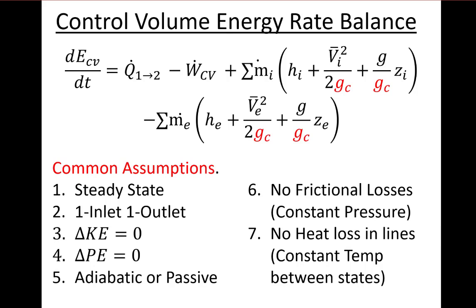That's not real. The pressure actually does decrease because conservation of mass tells us that the average velocity in the pipe has to stay the same. So we can't slow down. Friction can't take from kinetic energy inside a pipe. So what happens, at least if you're at steady state, is that it takes from the potential energy that's locked up inside the pressure.